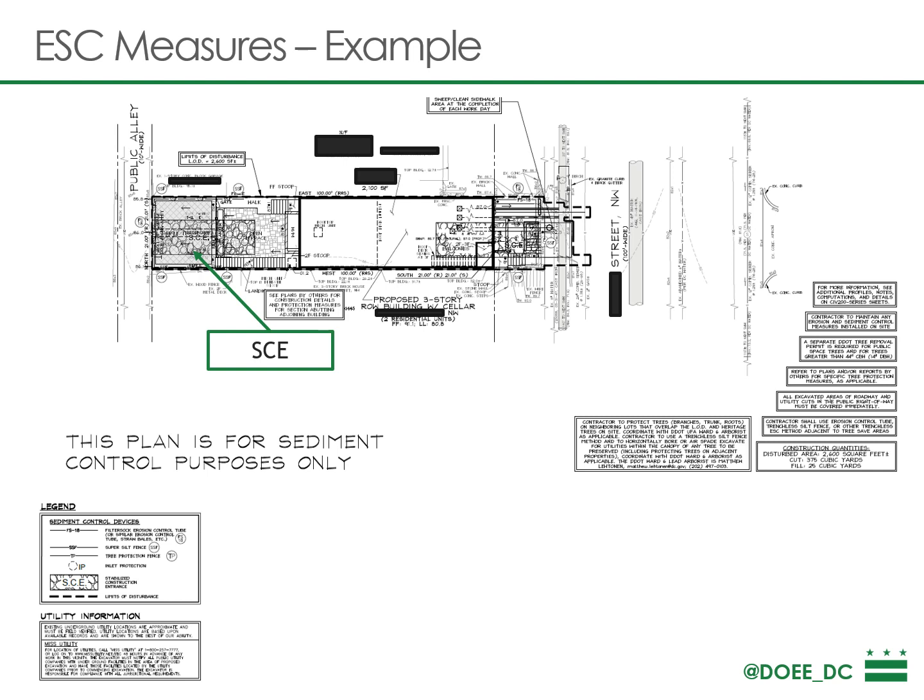If you cannot fit the complete sized stabilized construction entrance, you must note on the plans how you're going to accommodate. Perhaps you're going to start with a longer stabilized construction entrance and shorten it as construction progresses. Possibly you're going to have to use existing paved surfaces, that sort of thing. So anything that is not the standard 10-foot wide by 30-foot long stabilized construction entrance, you should specify and clarify what is going to be used to ensure that sediment does not leave the site by vehicular traffic leaving the site.